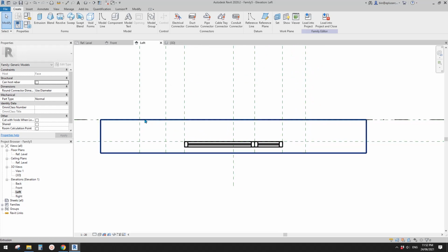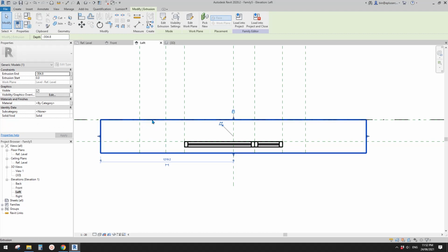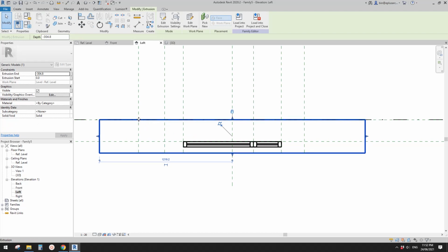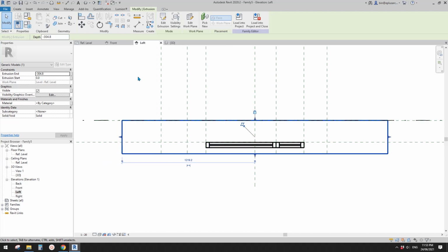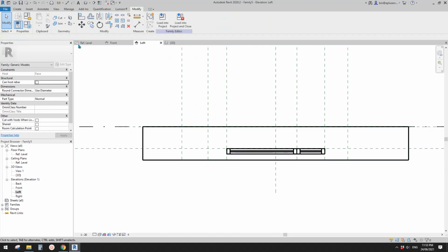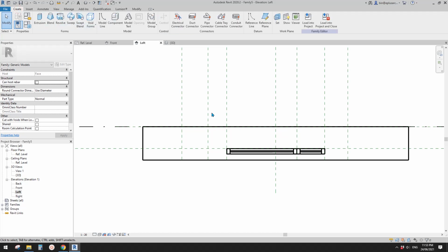For example, you just wanted to cut the base, but the void will cut the frame, will cut the glass, and sometimes it's very hard to uncut. Okay, so this tip is, when you try to create a void, create a solid first.